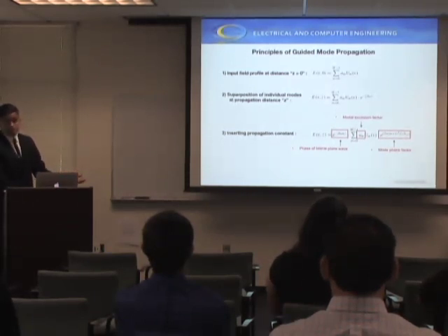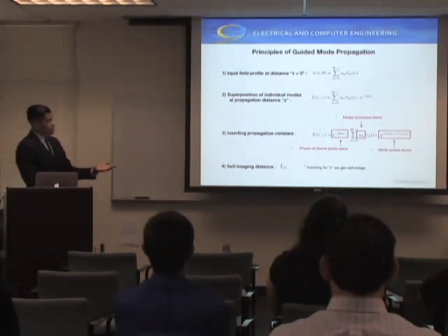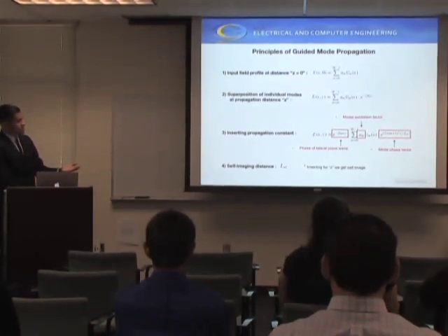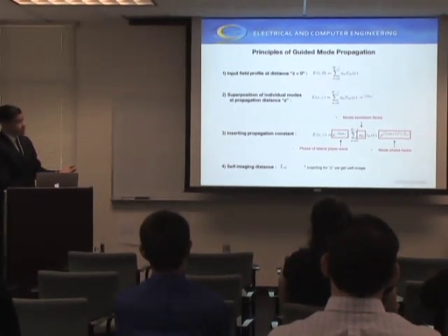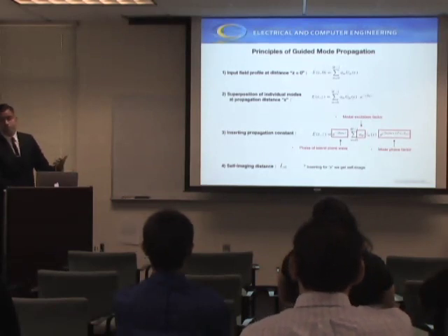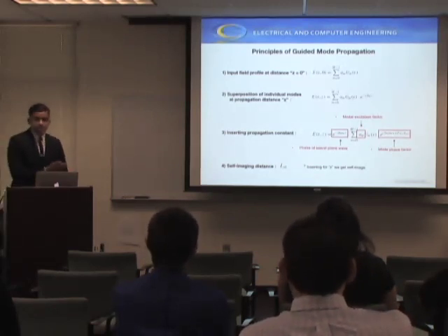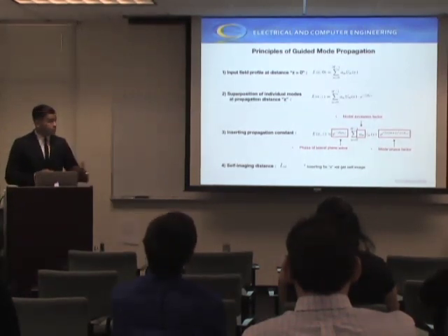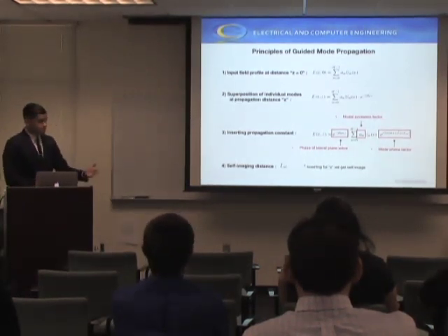If we look at this more closely and insert L sub Si for our z factor, we see that our mode phase factor would be equal to 1, thus giving us our input field varied by the modal excitation factor and shifted by the phase of the lateral plane wave. Basically, we can get an input field and at a certain distance get that same input field propagated through.